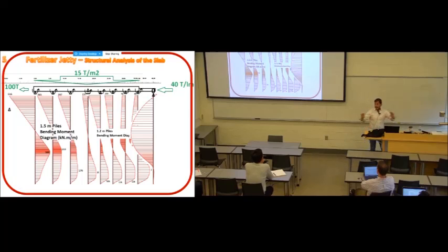Like here, the slab. To do the structural analysis of the slab, I put the slab on flexible joints, and I apply the moment that I saw on the pile tops from the geotech software at the node. And I keep all of them as rollers except for the front row. That's one way. Another way to do it is to make the structure with the pile that extends to the point of inflection, where the moment is zero, and put a roller there, a simple support. That's another way of doing it.